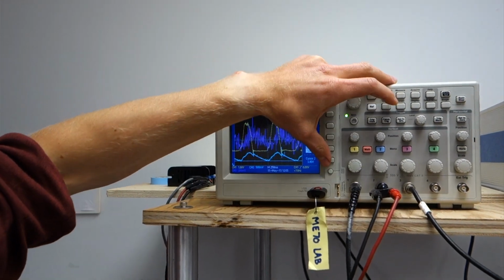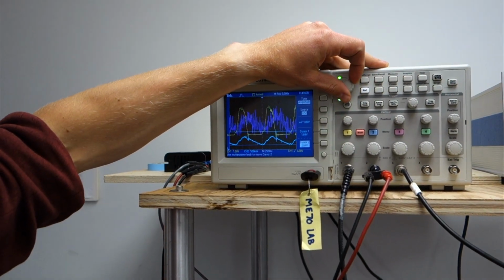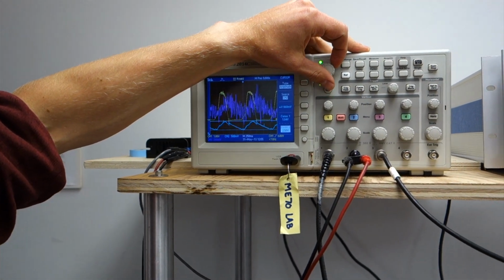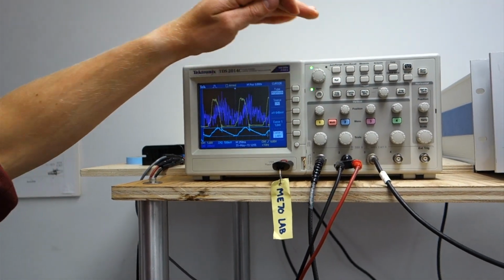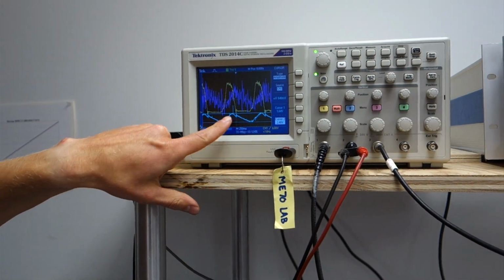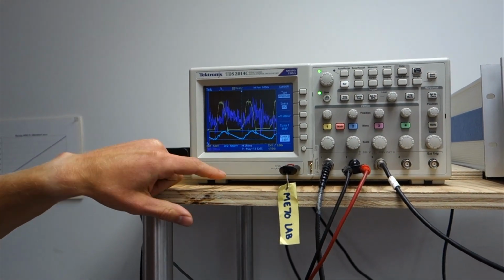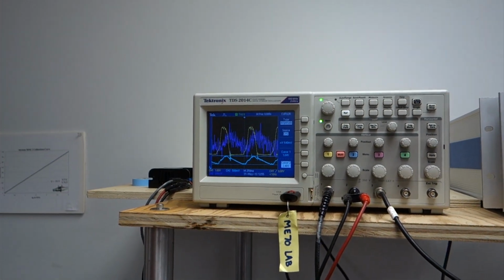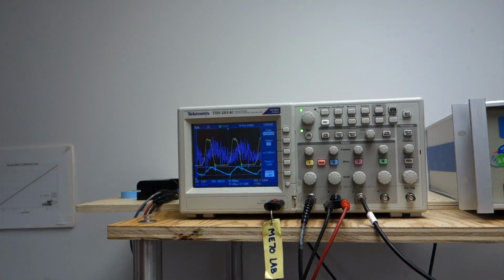We could gather information about that pressure, and convert from a voltage to a pressure in millimeters of mercury. In order to do that, we need the transfer function that goes between voltage and pressure. We've said that it's between 1 and 6 volts and 0 and 10 psi. So let's go to the board for a second and actually write out the transfer function for this sensor.